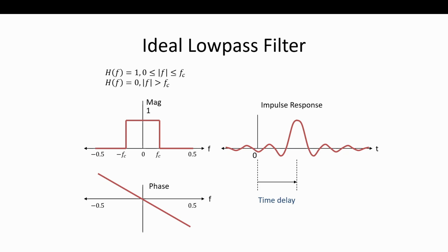And that's how we get the impulse response shifted to the right. And then we have to truncate it, right? And then we're completely causal. A filter that is completely symmetric will be linear phase, an FIR filter. So if it's completely symmetric, it'll be linear phase. So we're going to truncate it symmetrically so it's still balanced that way.